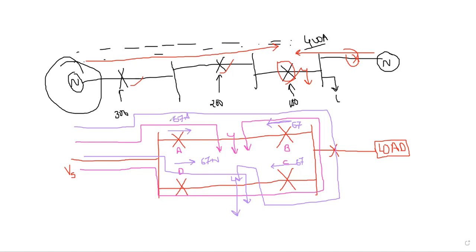So what generally we will do is, we will place always a directional feature on the paralleling side at the load end, and on this side general overcurrent protection will be enabled. So it is seeing the fault in both directions, as a kind of a backup for the distance as well as for this. So always, if you want to protect the system in a single direction, then you have to use the directional overcurrent relay.